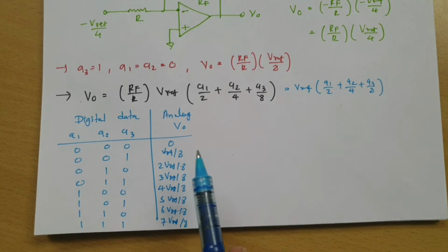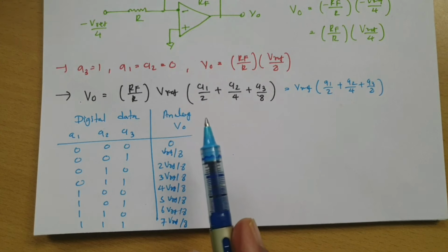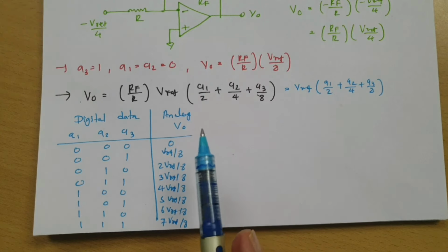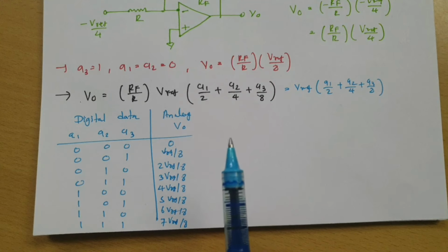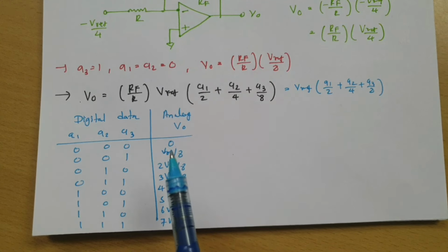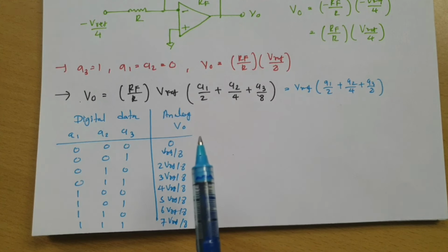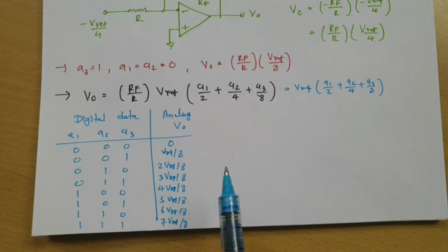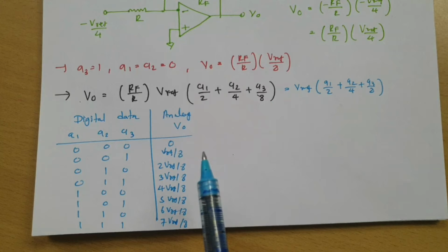And see, this circuit is quite better compared to the binary weighted digital to analog converter, as we just have two values of resistance in this circuit, right? While if you observe the previous circuit, there were many resistances. I hope that now it is clear to all of you how this R-2R ladder is useful. And in the next video I'll explain one example based on the R-2R digital to analog converter, which will resolve your understanding further.